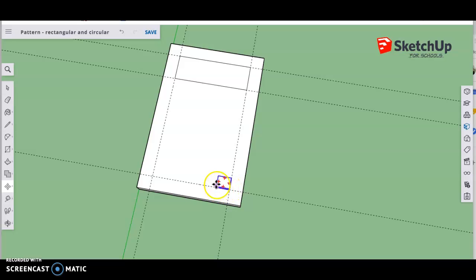I'm going to click here, press Option or Control, and I'm going to press the right arrow so it's constrained to stay on that red axis. If I wanted an external array, I would click where I wanted the next key, and then I would say, let's say I wanted 5, I would do 5x, return, and it's going to give me an external array. But I'd have to do some math to see how big that spacing is, to see where I wanted it to end. So I'm going to undo, and instead I'm going to do an internal array.